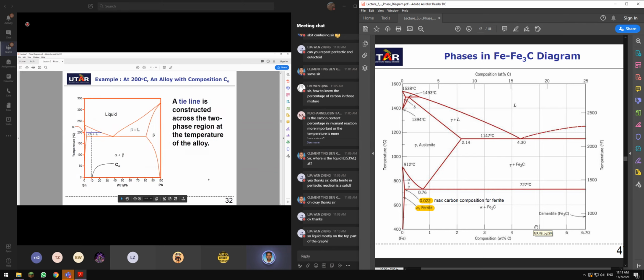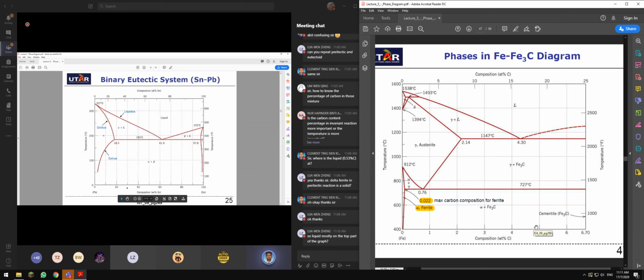In the previous lecture, for example, what is this? Lead and tin phase diagram. It looks like this. So this is all liquid, right? At the top of your phase diagram, all is liquid. When you cool down, it changes to semi-liquid. But here, eutectic reaction, eutectic invariant point, eutectic point, liquid directly to solid.